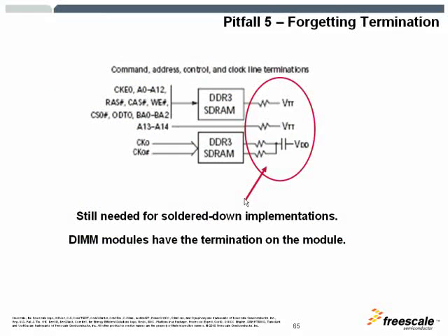Do not forget your terminations. Here you see the terminations that are for DDR3 specifically. We've noticed that people might miss them or try to configure them similar to DDR2, and that is not correct. So pay attention to the termination required for DDR3 if you're laying out the parts on your board and you're not using a DIMM.